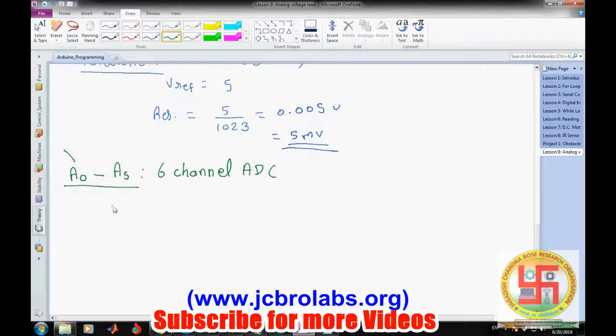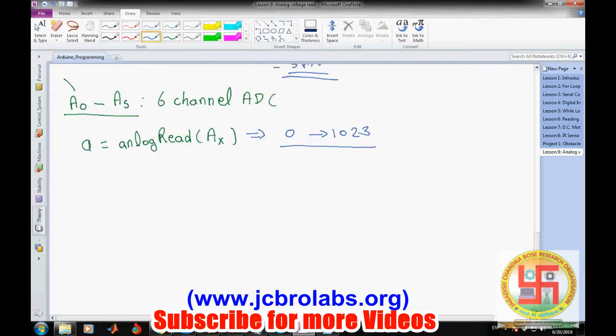And similarly in Arduino we have a command like analogRead, and here is the channel number, let's say A of X, so X could be 0 to 5. This is the command which directly reads the analog value and gives output in the integer range. So this particular command gives the output in the range of 0 to 1023. Okay, so it gives the digital number in an integer format.